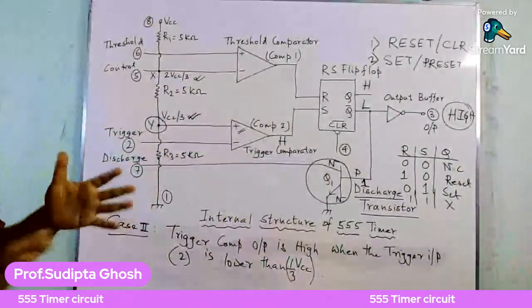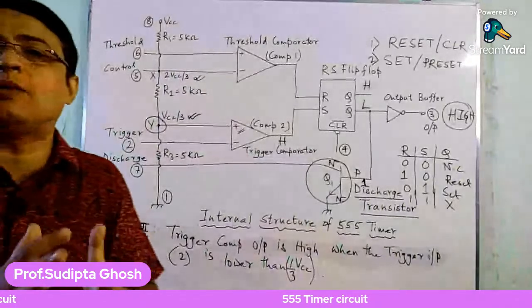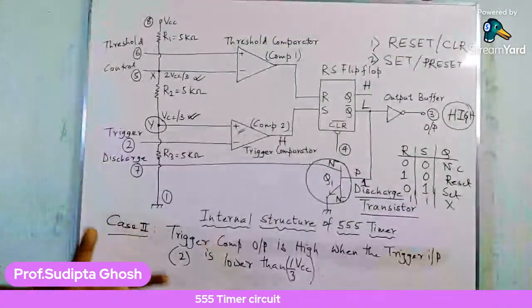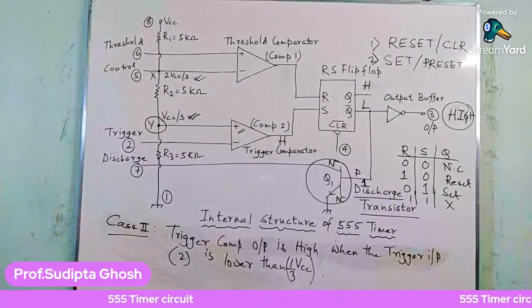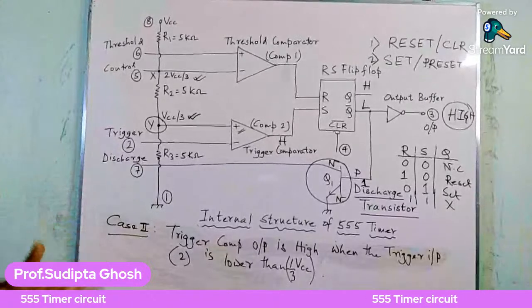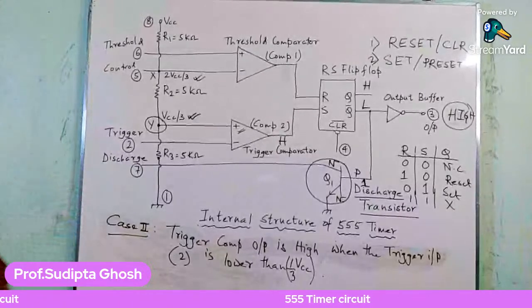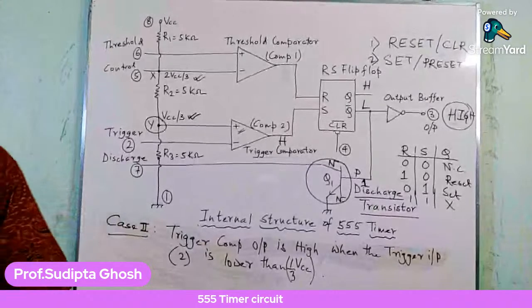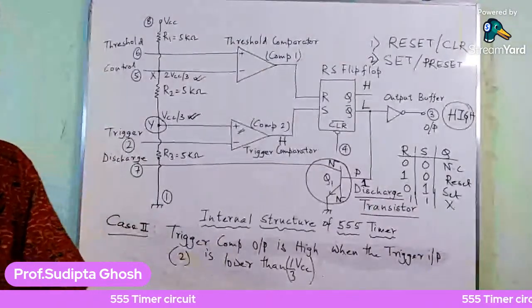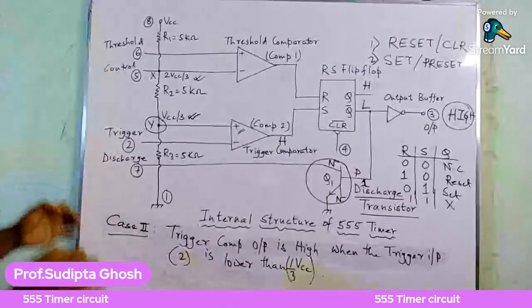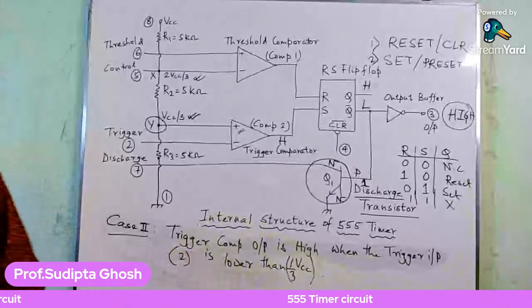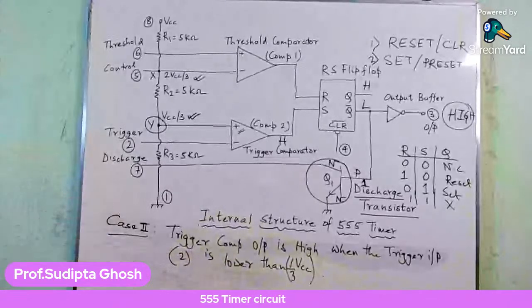In our practical classes or in our syllabus, we are not going to disturb the 555 timer internal circuit, so that pin should be avoided, or that pin should be grounded.